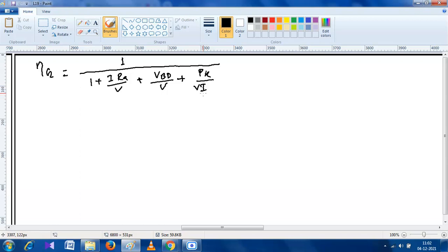Ayush, Manish, did you understand or not? So what is Pk, sir? Pk is the constant losses. The three losses are constant, which basically depend on voltage. Though the voltage of the generator or motor is nearly constant, we write these three losses as constant losses.